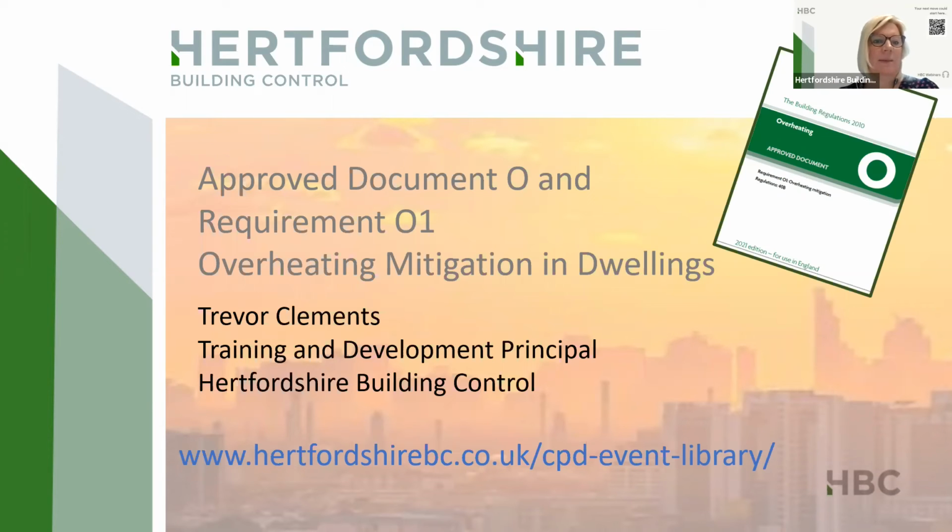Thank you. Next one: because of security and protection from falling, I cannot see, in dwellings and bungalows, a scenario where you wouldn't need to do the TM59 assessment. Could you advise on a scenario where you could actually use a simplified method of calculation? Yeah, I think you could still use a simplified method, but you would have to look at the geometric free area that is provided, and take into consideration whatever guarding or shuttering method you use. You could still relate to the tables, but guarding and shutters would have an effect that you'd have to build into your calculation.